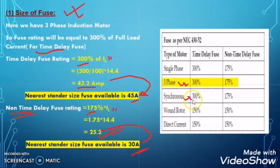If we have a synchronous motor, then the factor will be different. If it is a wound rotor motor, then the factor will be different. Same for the direct current motor, it will be different. So we have to check for which motor we are selecting the fuse. According to that, we have to find the factor to multiply with the full load current to get the correct value of fuse rating. Hope I'm clear.